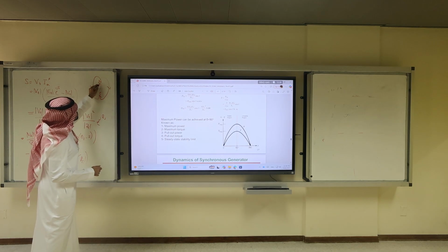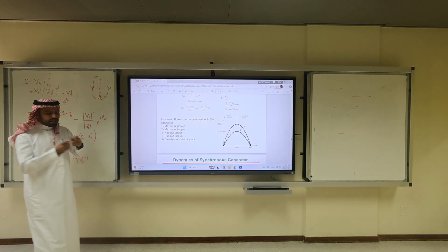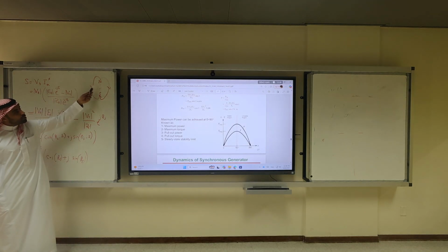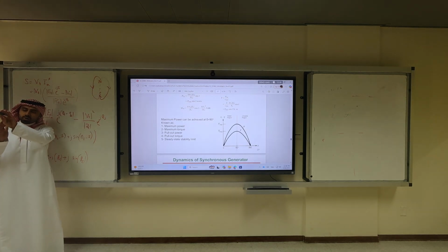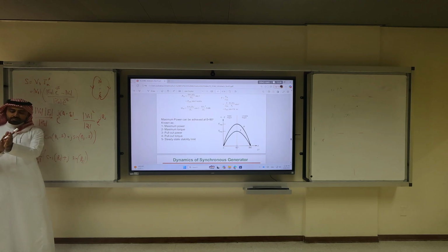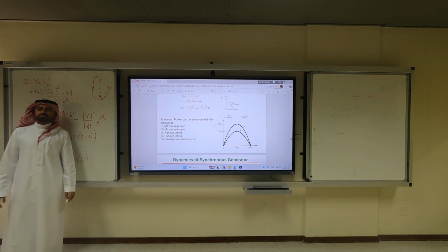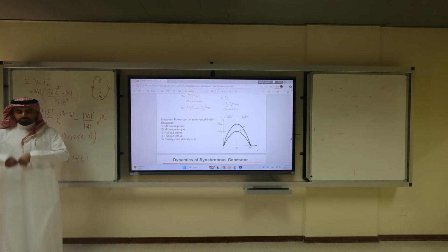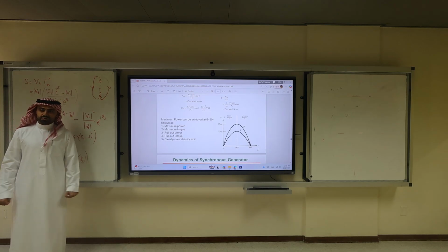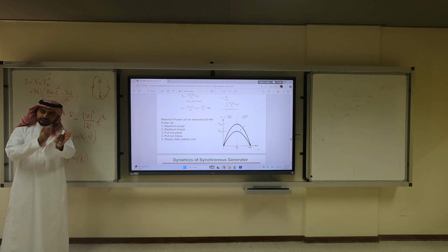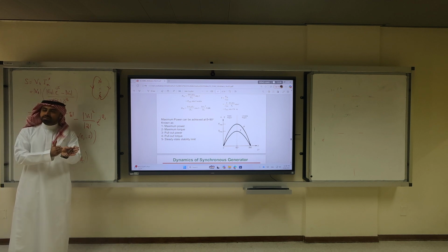Always you would find the south. The idea of the synchronous machine is you're pulling the magnetic flux toward each other. If you add more load, they will slip, they will follow each other. But they will be in a uniform way. You cannot control them. Once you let them synchronize, naturally they will follow each other. But yeah, it's true. If they are aligned directly, delta is zero, means power is zero.